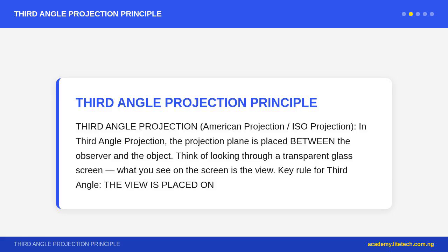Converting a drawing from first angle to third angle, or vice versa, requires repositioning views. If you have a first angle drawing with front view, center. Plan below. Right side view on left. The equivalent third angle drawing has front view, center, unchanged. Plan above, moved from below. Right side view on right, moved from left. The actual views themselves, the shapes drawn, do not change, only their positions relative to the front view change.